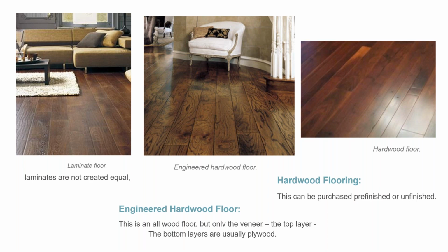I am not a fan of laminated floors unless they're serious. This one is a pretty nice one. It's very thick. This is an engineered hardwood floor, some of which can be sanded up to 3 times, depending on the quality. And then you've got a real hardwood floor, which can be sanded multiple times.